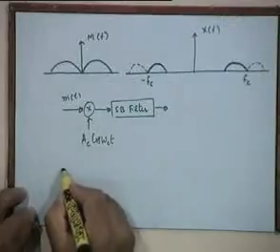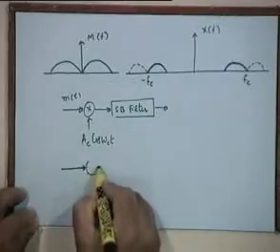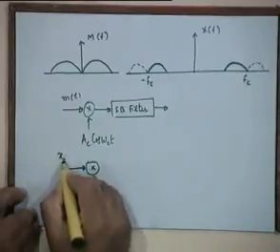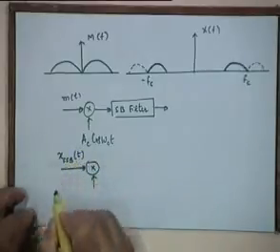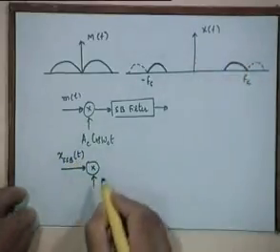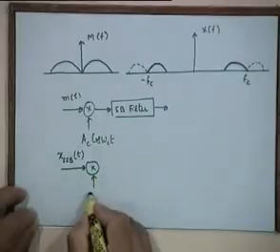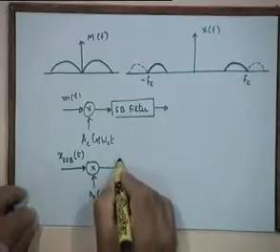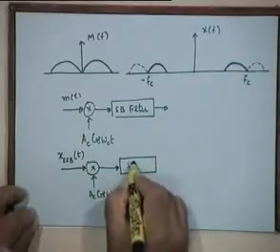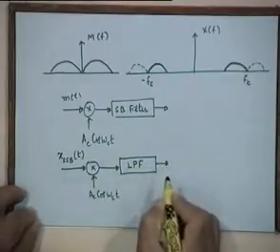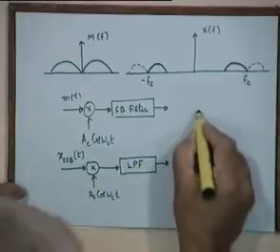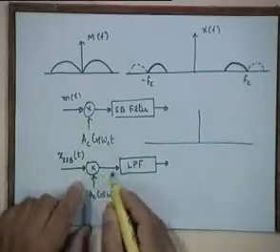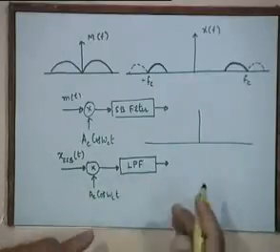And like we discussed, the reconstruction is possible by the same process that we have for the DSB-SC signal. So, here is your SSB signal coming in, right. This is your SSB spectrum, this is the SSB signal in time domain. You again multiply with the carrier and pass it through a low pass filter, just like what you were doing for the case of DSB-SC, right. In the frequency domain, as a result of this multiplication, the same frequency translation is happening again.